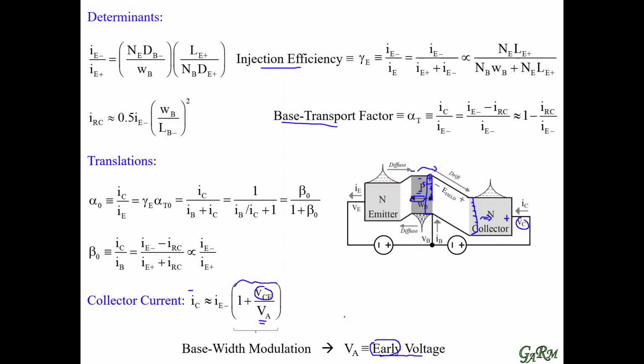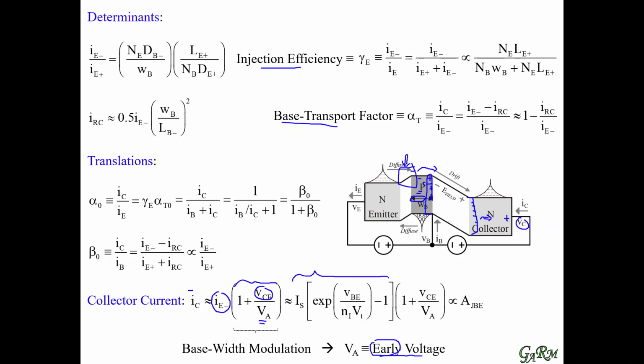But now we go back to this emitter electron current, and that's basically the forward bias current across this junction. And that's a diode, so it's basically just a diode expression. So what we see here is a diode current, and that diode current is pretty much the one that is describing the electron current in the emitter.